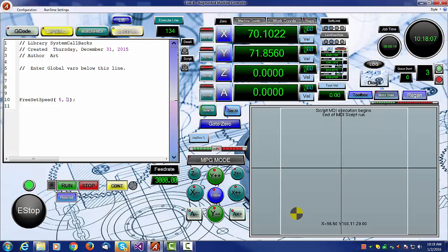It's not really stopped, but at 1 millimeter per minute, it could take a while to do much. So let me just speed it up a little bit. Here I've got it set to a speed of 22. So this will be 22 times whatever the steps per second is for the unit. These displays follow the same settings that are selected up here between machine, work, and steps. And you can enter a number into them to zero them. For example, these ones here, I could just enter 0 and zero the display just like any other DRO.